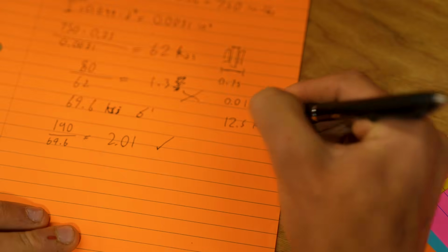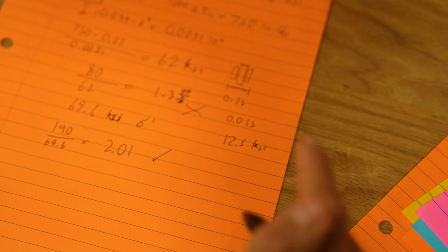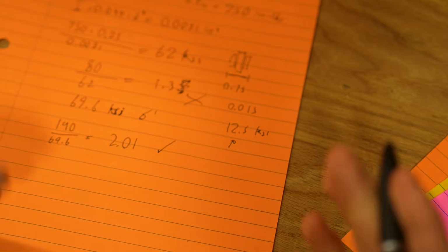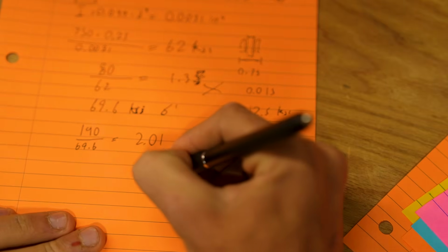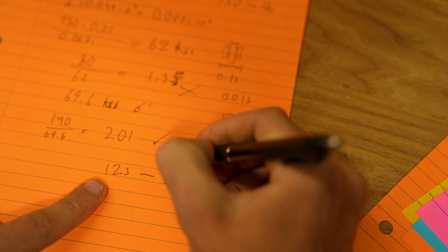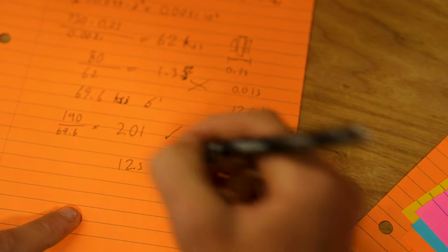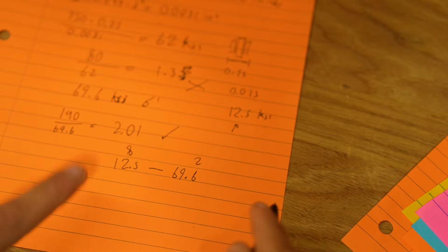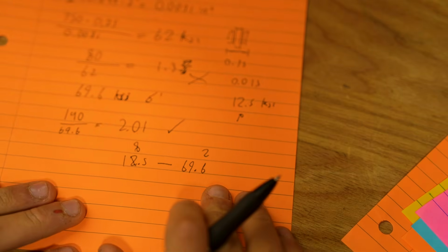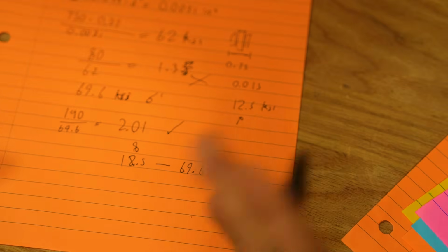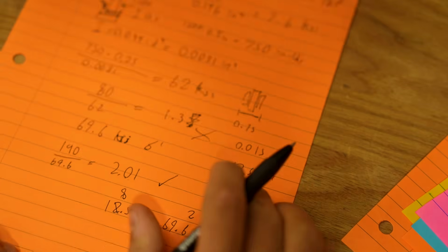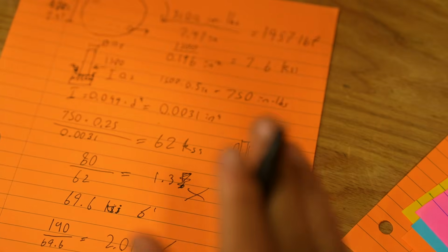12.5 KSI. So this is what would be called a bounding analysis. So this is the non-conservative load case assumption. The reality is that we're likely somewhere in between 12.5 and 69.6, depending on how load is shared, which is going from a safety factor of 2 to a safety factor of like 8 or whatever, because this is actually like 18. Okay, so this is what engineering kind of gets down to: the trading off of these equations and knowing how to make assumptions and how those assumptions impact your calculations. All right, but overall, the nubbin is validated.